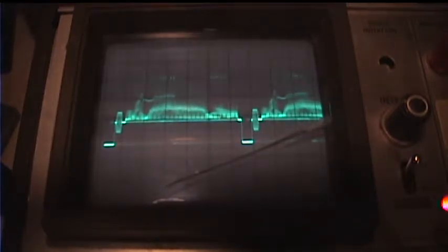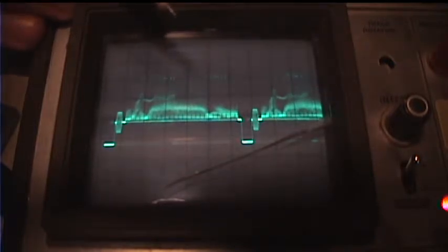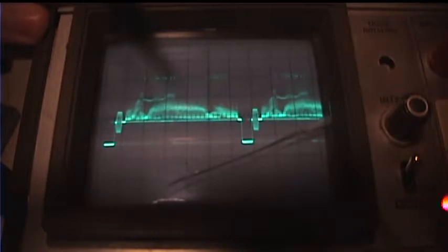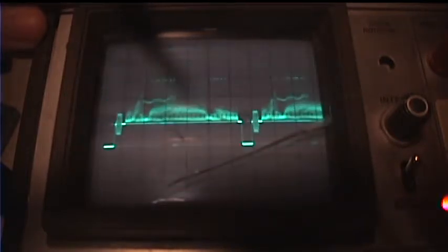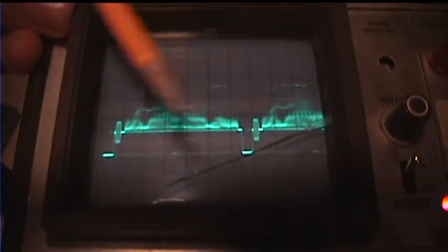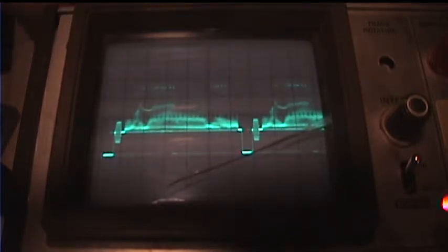And that's because video signals are AC coupled. So the actual DC level doesn't matter, like if we move the signal up or down. What your TV looks at is how far above the sync pulses it is. So this will come in handy when I explain the circuit now.